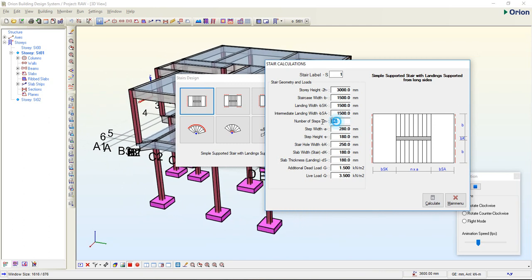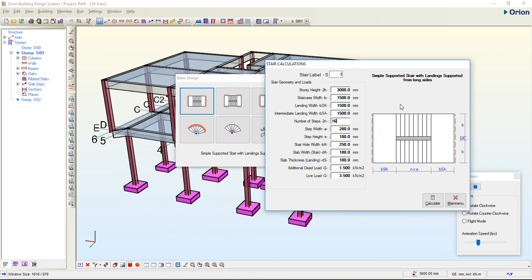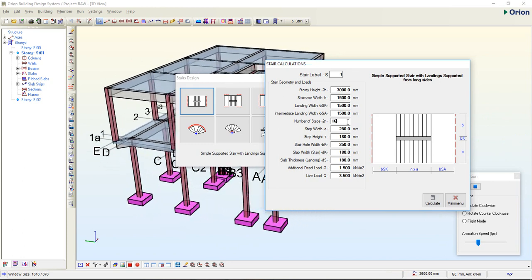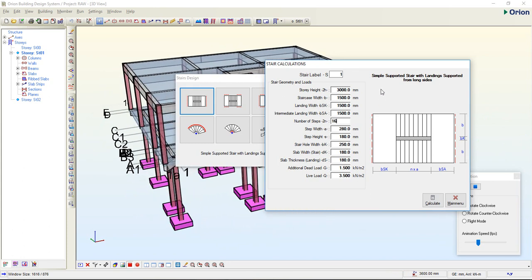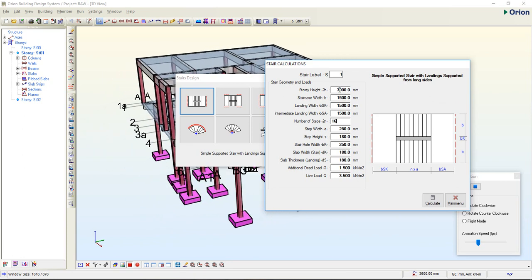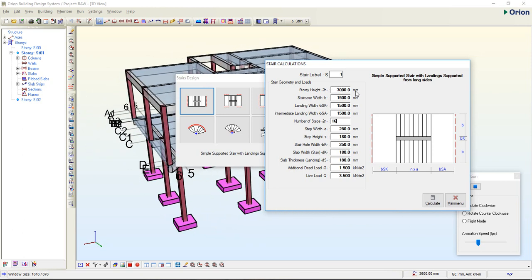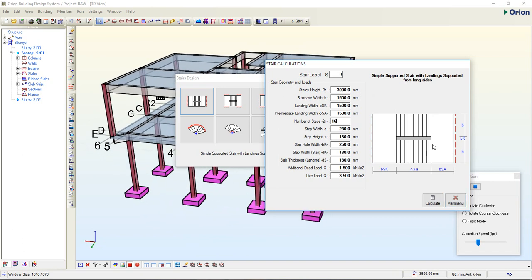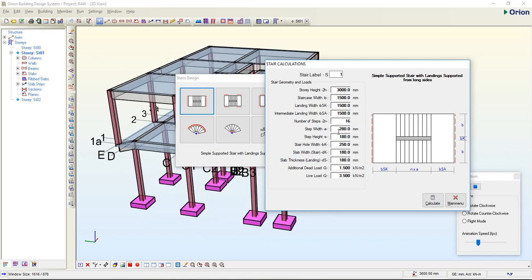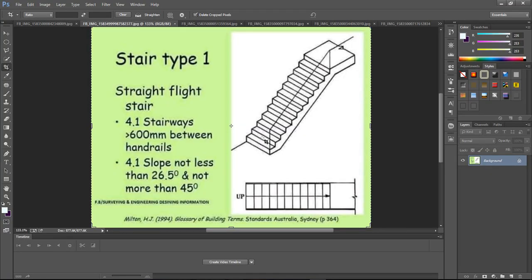Usually you don't just determine the number of staircase on yourself. If you are doing a good design, to know the number of steps that your staircase, your flight, is supposed to have, you have to divide the height of your story with your riser. Before we go into that, you're supposed to know what we call a riser. A riser is this.